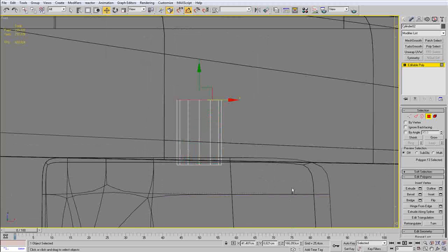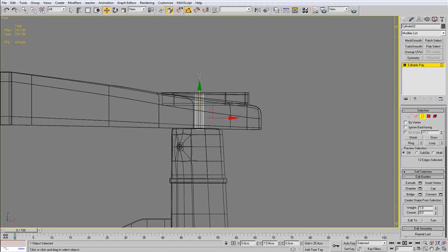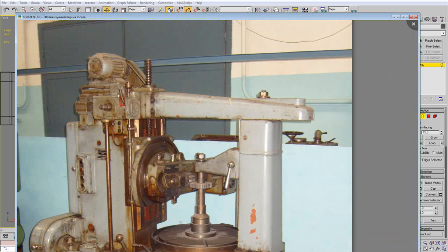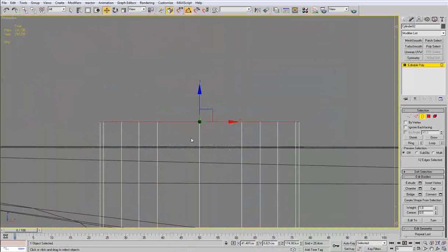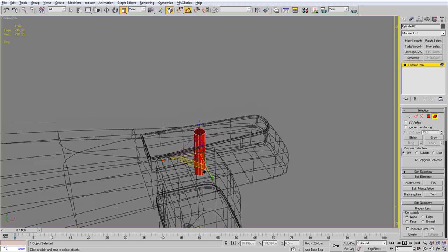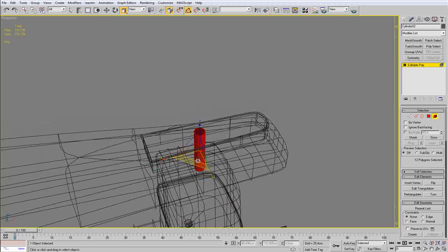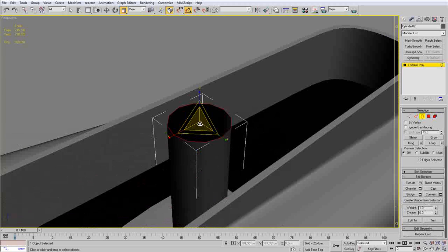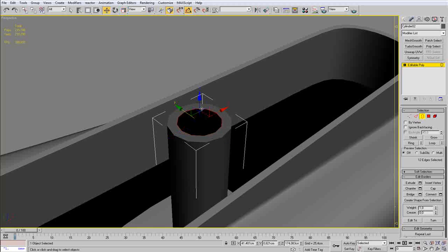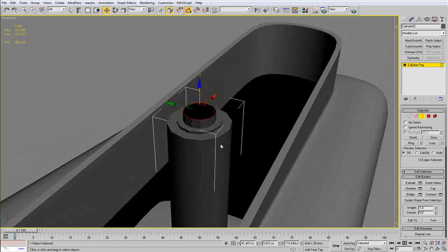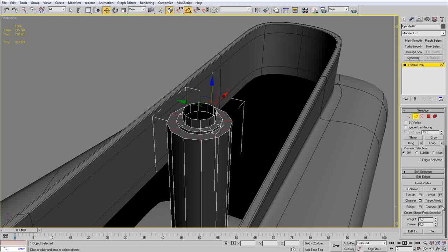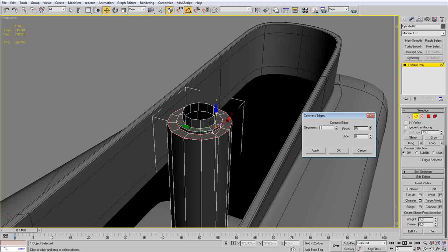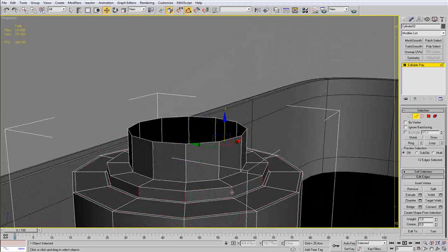Okay, start off with a cylinder, and I delete the top, the bottom polygon, and move the top one upwards. Then I'm going to adjust the thickness a little bit, as I think that it wasn't big enough, and I'm going to go ahead and start creating the detail at the top. I'm going to harden the edges like you see here.